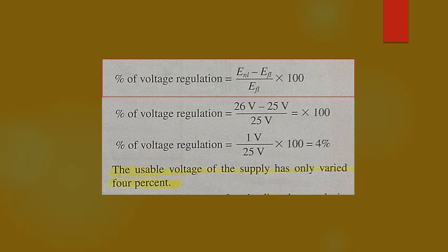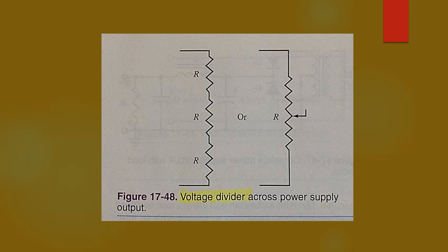A further advantage of preloading the supply is an increase in the choke filtering action. The resistor allows current to flow in the supply at all times. A choke has better filtering action under this current condition than when current varies between a low value and zero.